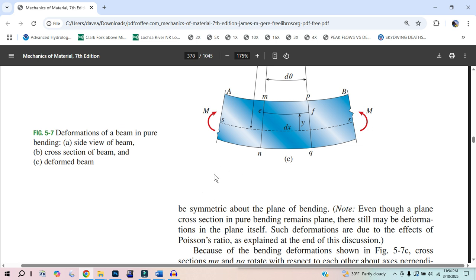So sigma would be the stress, and this would be 50,000 pounds is equal to E, your constant, times 0.002. What do you multiply by 0.002 to get 50,000? Well, a hell of a big number, and in this case for steel it's 29 million. That's the modulus of elasticity, which is just the equation.